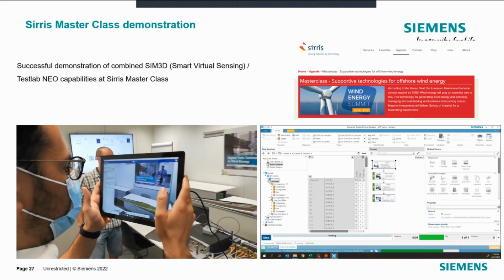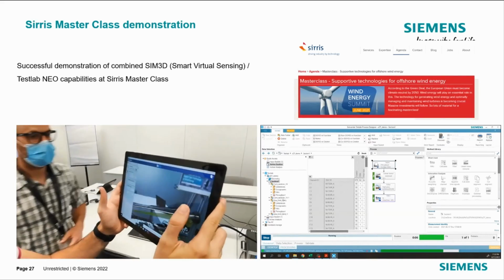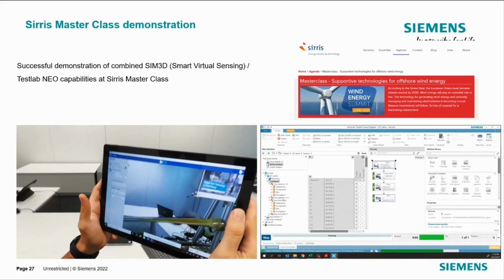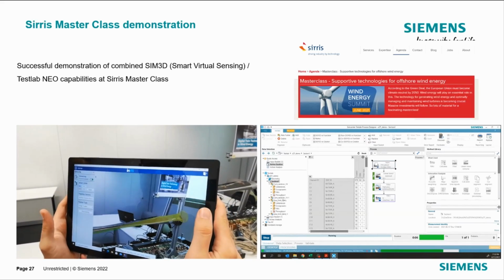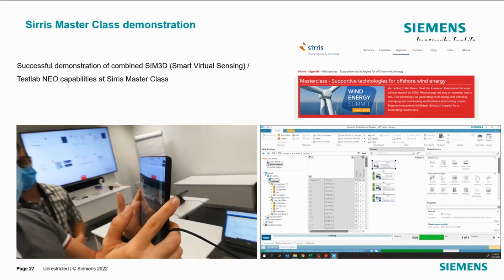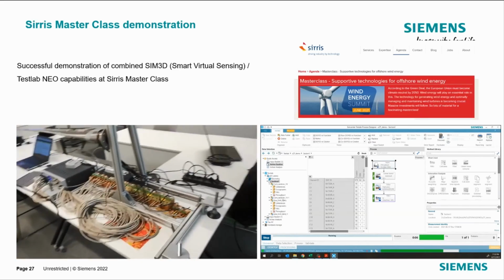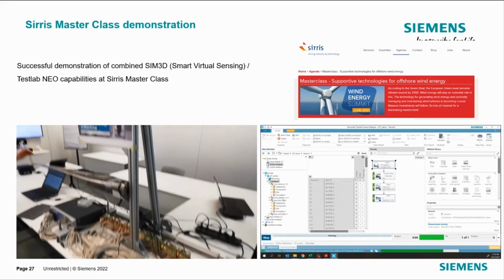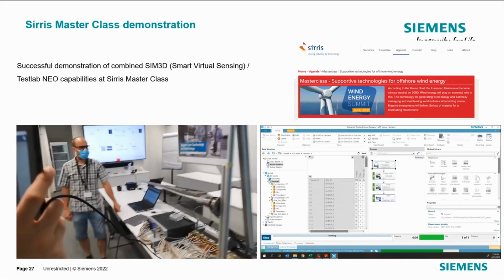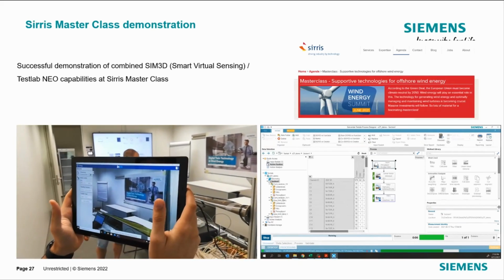So we were able to align the two structures, the physical and the digital twin, and then reconstruct the full field based on a few strain gauges that were installed on the blade. You can spot them on the top surface of the blade. And then we were able to track this in real time. Here you see the equipment that we used, and there's an IPC able to combine the FMU, the packaged FE model, with the test data.